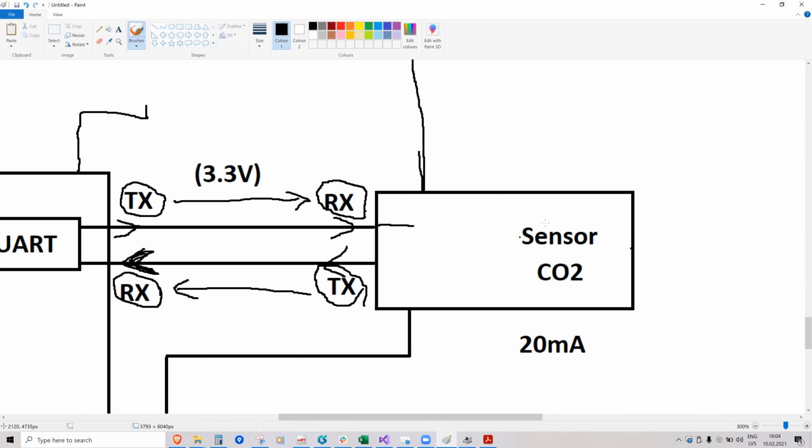And before it goes to the sensing element in the chip, to protect it from electrostatic discharge, there is a pair of electrostatic discharge protection diodes like this. And it actually exists for both lines. All lines of all chips nowadays have ESD protection diodes, which connect each pin through a diode to power supply and to ground.